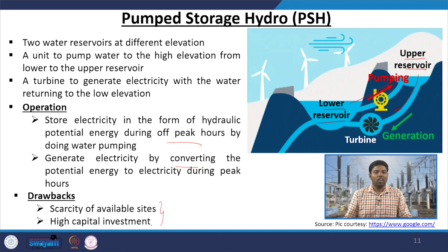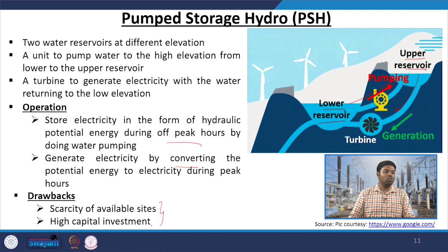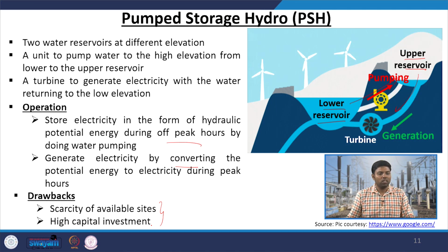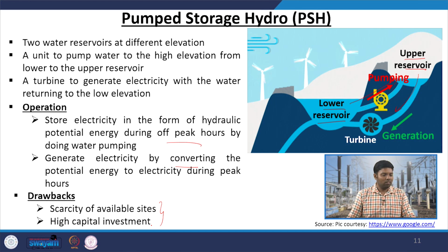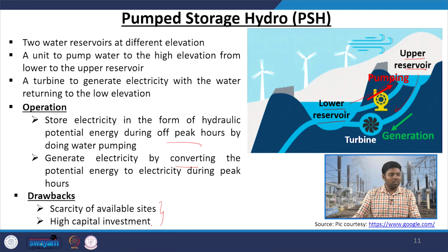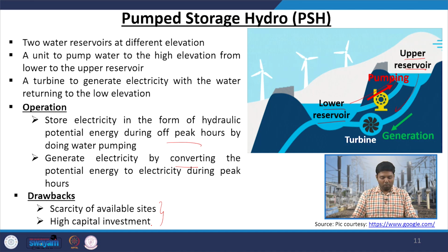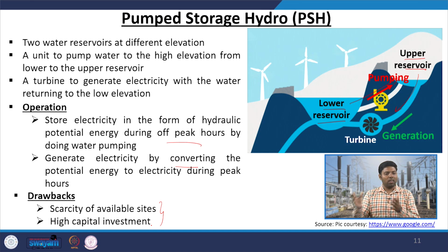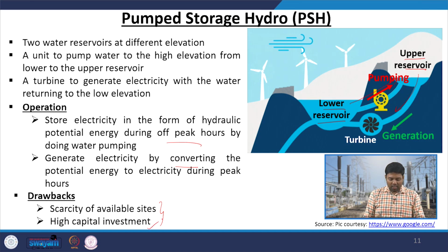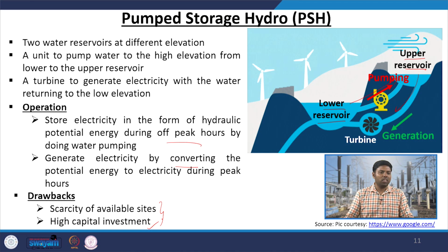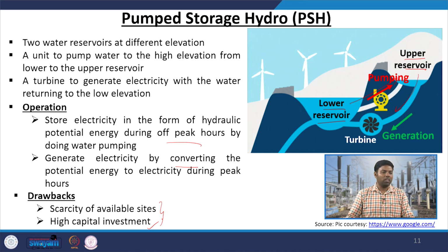First thing is that you need a proper geography to build this pump storage hydro facility. You cannot build it in the plains. That means you cannot build it anywhere you want. You need proper geographical sites for building the upper and the lower reservoir. Second thing, building reservoir dams always takes a huge amount of capital investment.